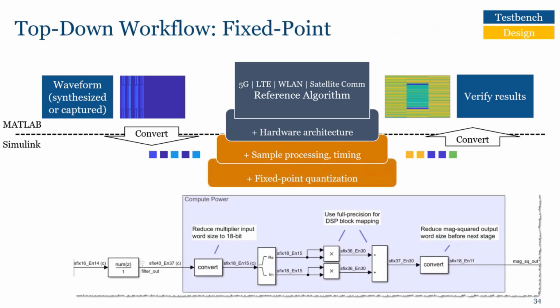One of the last steps before going to implementation is exploring the data type effect on our architecture. Like I said, we are always modeling in MATLAB, and our first models are in floating point. Later on, we need to see how the fixed-point quantization is affecting our model. So for a first iteration, we can let Fixed-Point Designer go through all the conversion that is needed, but later on we can explore the effect of this conversion on a subsystem level